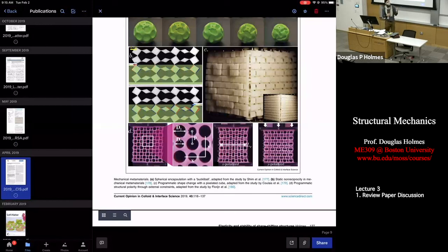One of the areas where these types of mechanical metamaterials are really being utilized on a larger scale is with deployable structures for aerospace, especially the origami stuff, where you're going to send some sort of solar satellite out into space, and you want this thing to open up and deploy in a particular way. And these types of structures can be scaled up to that size where we know what the mechanics are going to do.